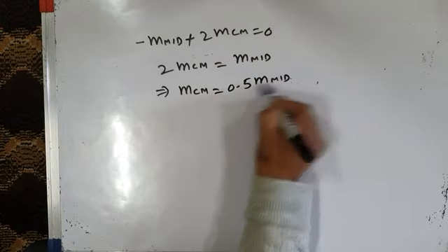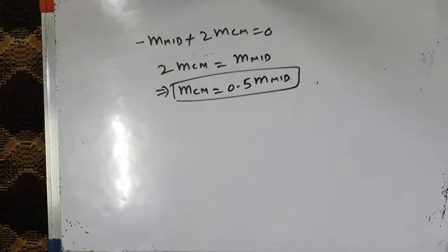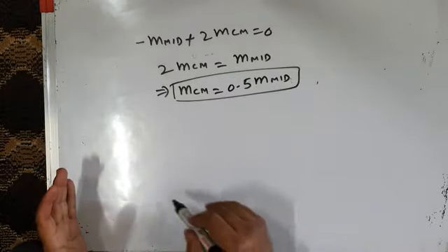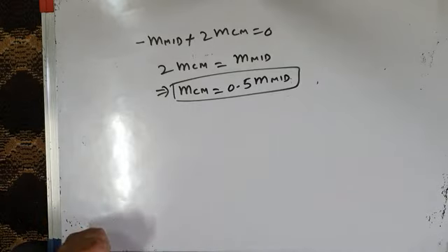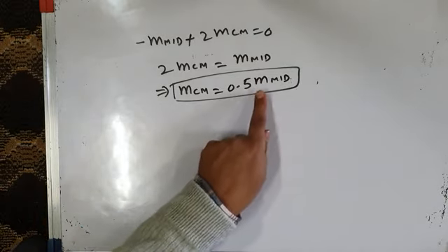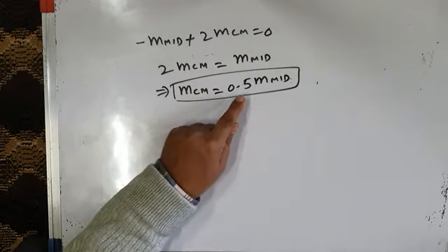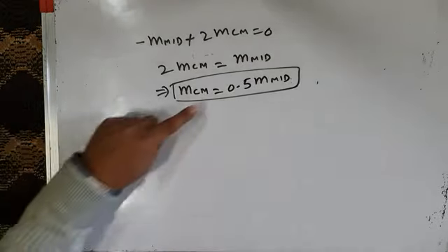So this gives us an idea of how to calculate MCM, the common mode signal. What you have to do is draw the three original sinusoidal modulating waves, and then take the middle value after each 30-degree interval, and take half of that, and that will be your common mode signal.